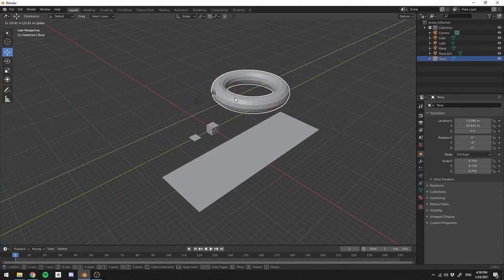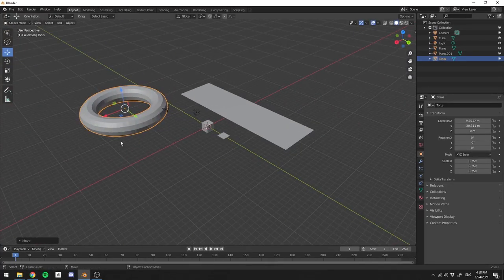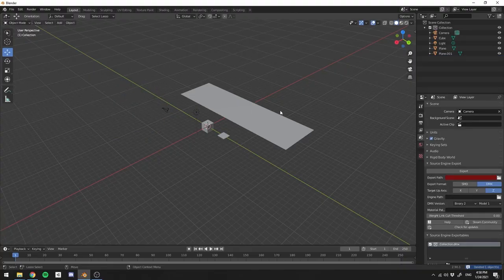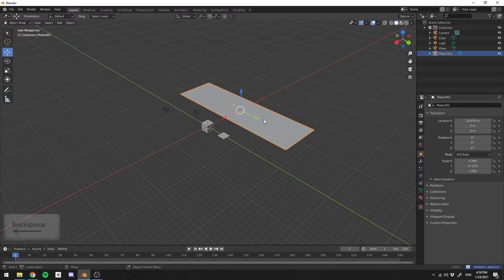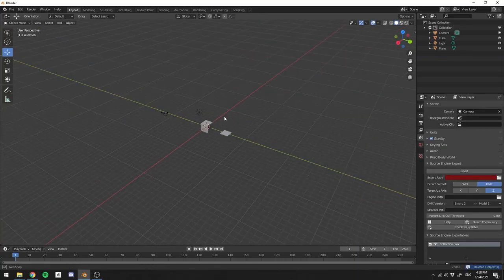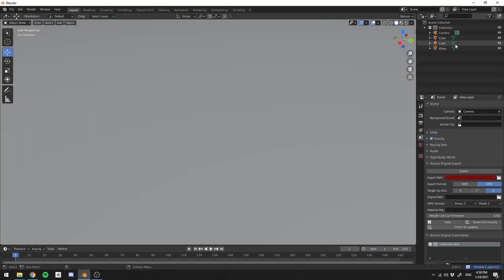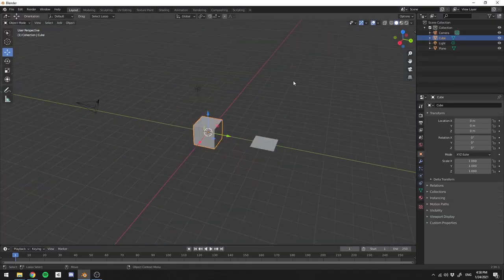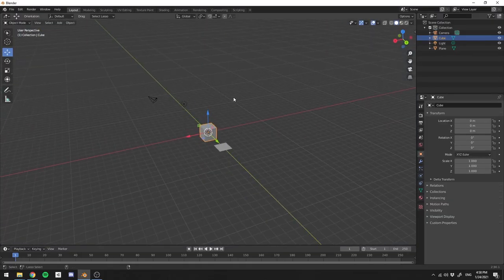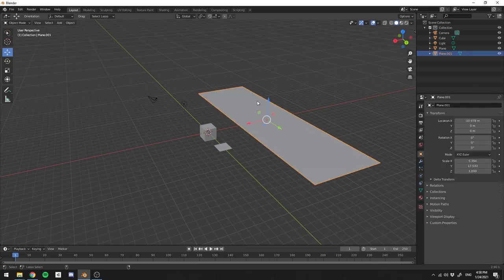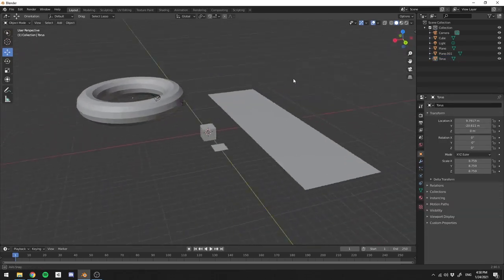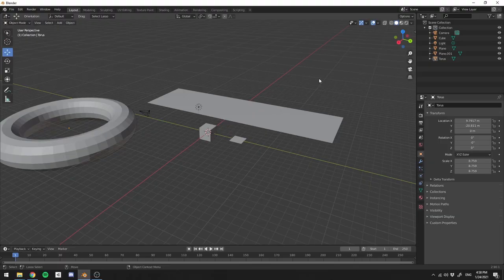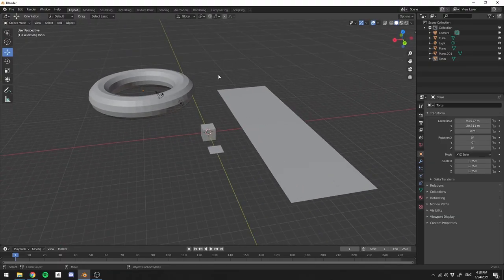The next thing that I want to show you is how you can delete objects from the scene. It's pretty easy. You just select the object and hit the Delete key on your keyboard, or select another object and press Backspace on your keyboard, and you just delete it. And if you made a mistake, you can always press Ctrl Z to go back and fix this mistake. If you delete something by accident, you can always go back and press Ctrl Z.